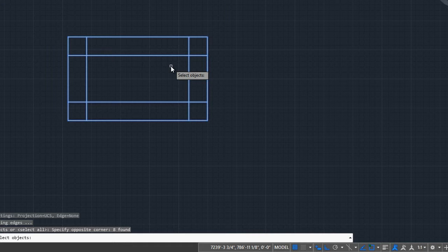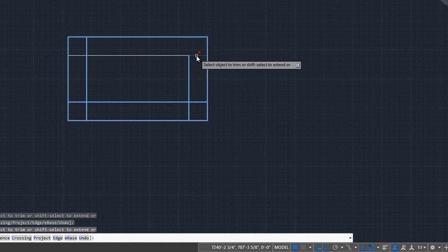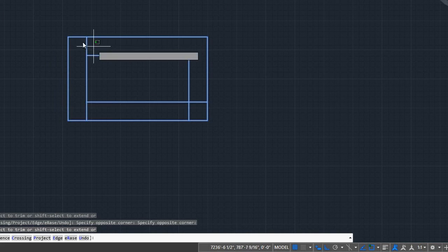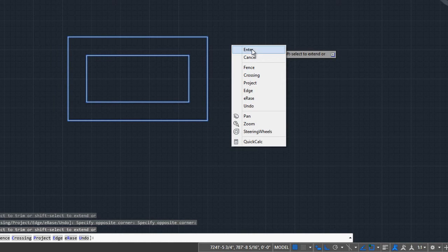You have to be a little bit careful about this because it can start to come back and create a little bit more work. However, if I just select everything as my cutting edge and hit enter, I can select these individually, or as I noted, I could actually use my selection tool as this fence and kind of kill two birds with one stone. No offense to birds.